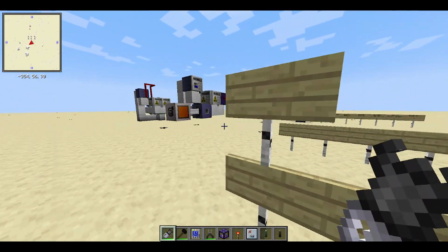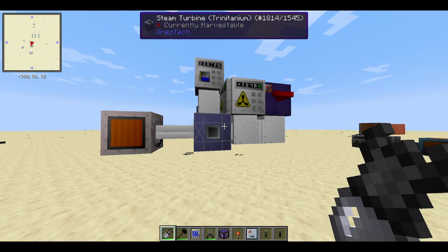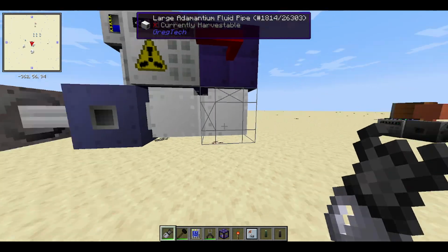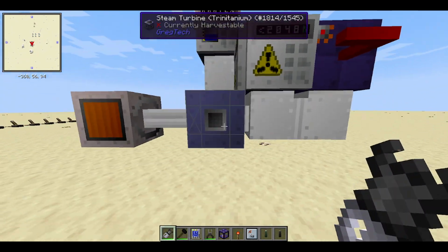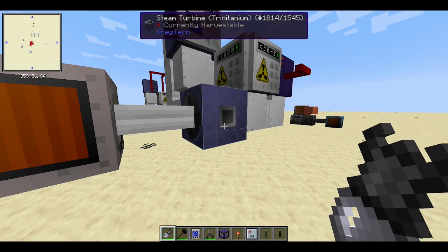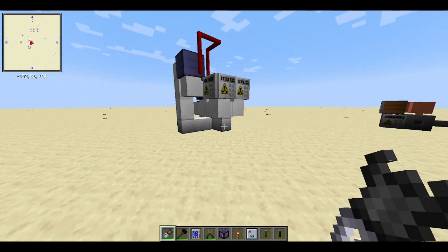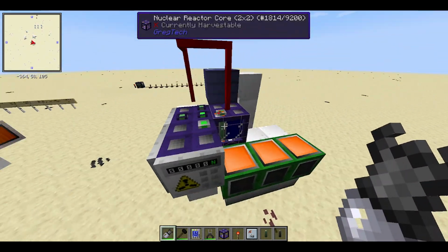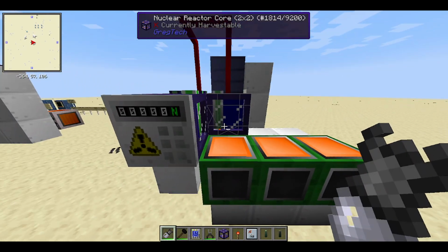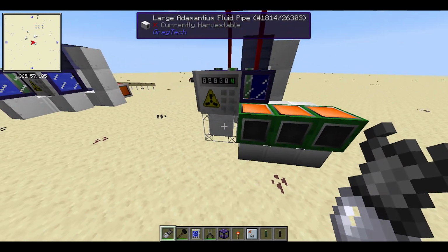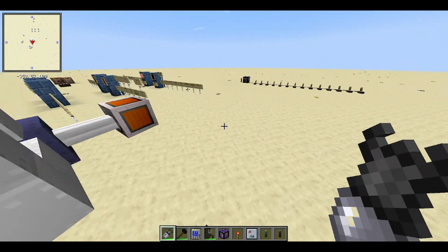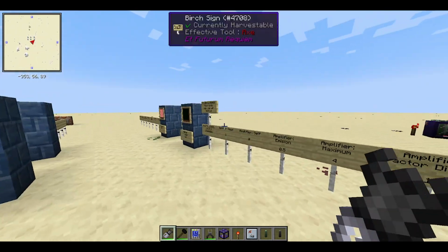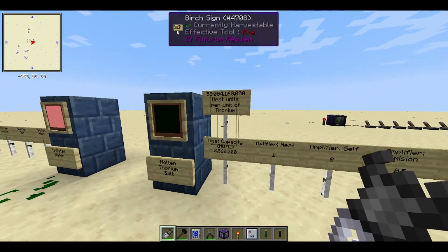Well, molten thorium salt doesn't work like other coolants in the reactor. So if you remember how the first kind of reactors we built worked, they used distilled water and they generated steam, and then we used that steam to spin a turbine. And with the other kinds of coolants, like in our breeder reactor, with sodium, you get hot sodium, or with other coolants, you'll just get their hot coolant, and then you use heat exchangers to extract the energy out of that coolant. Molten thorium salt doesn't work like either of those kinds of coolants.